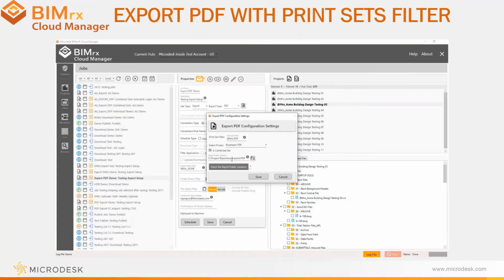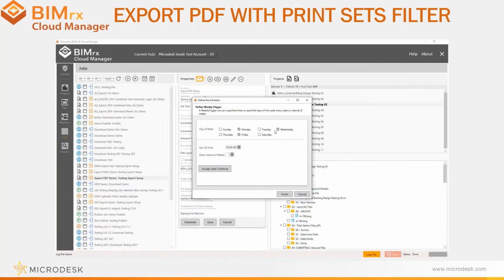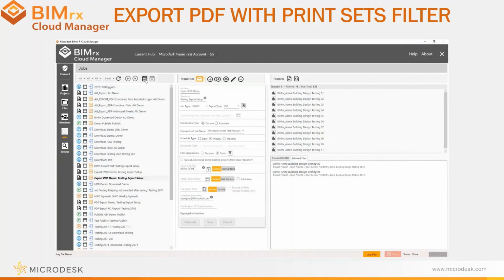Next, I'll set the export destination and then select the Revit version year and then save the settings. Now I will schedule the job and I'm going to have it run Monday, Wednesday, and Friday each week at 4:28 a.m. Finally, I'm going to use the static method to select the models I want to include in this export job. I add the project and then I select a model in this project, and then I'm going to add another project and select a model from that project. I will then save and then I will deploy the job.